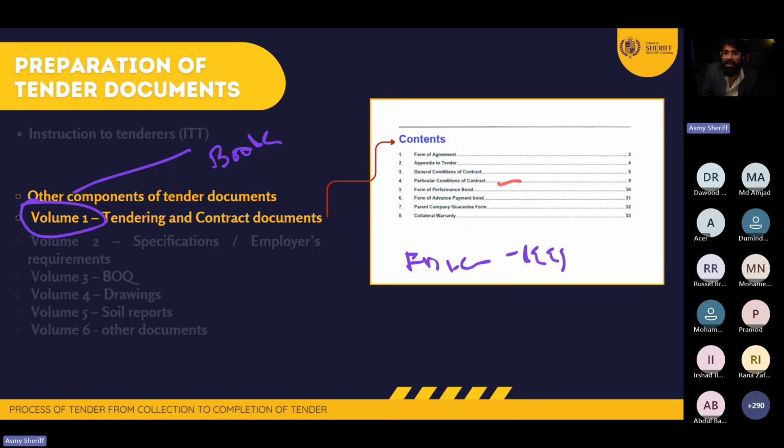I'm going to collect the general conditions. Normally, you are not going to put the FIDIC inside that. What you will do? You will make a small paper. In the paper, you will mention the general conditions of the project is FIDIC 1999 Red Book, because it's freely available, or maybe the contractor can buy it. And one paper I will put that.